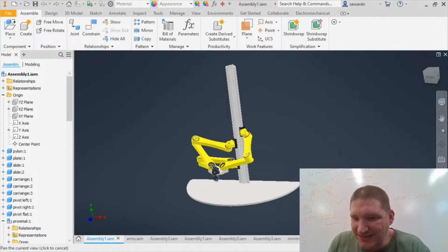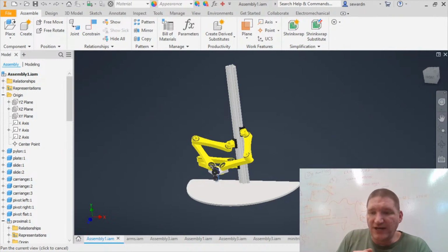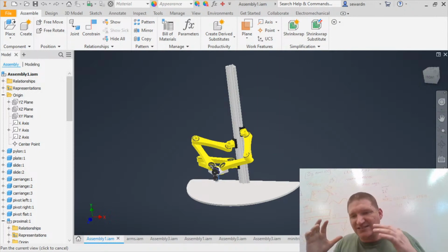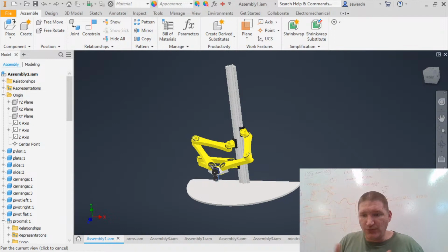All right, everything working? Sounds good. Okay, it seems like TMC enables you to drop the endstops, since they sense the stepper stall. Not sure if they're accurate enough for bed probing too. So yeah, TMC or Trinamic drivers can tell me if I stall, so I will not have any endstops. I'm anti endstops. If you can get rid of a part, no part's the best part. In fact, since the resolution's the same everywhere, I will start early on by just putting the effector on the bed and saying go. It doesn't actually need to know where it is. It just needs to know how to move from there, and everything's consistent throughout.